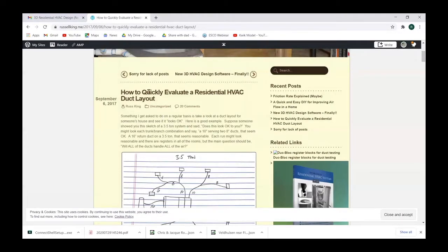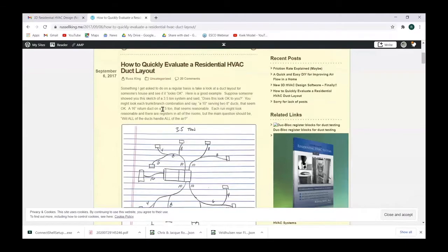So in our software, you would look it up in Manual J. You would say, okay, I've got this wall. What does Manual J say the framing factor is for this kind of wall? And you type that in, and then it'll do the correct framing factor. I just keep saying friction rate. Framing factor. Yeah. Framing factor.